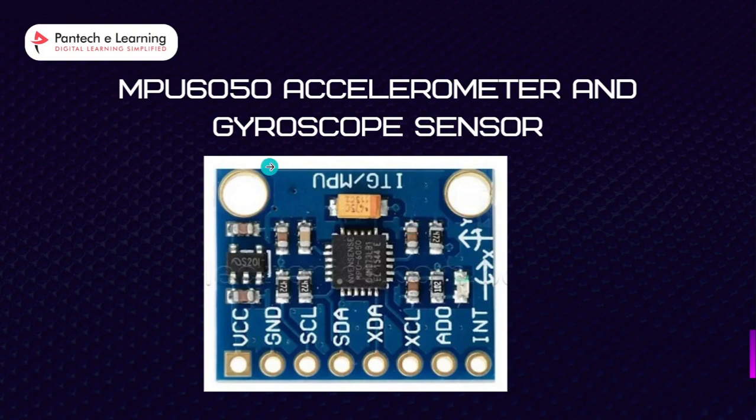Coming to the MPU 6050 accelerometer and gyroscope sensor, this is how it actually looks. This is the world's first integrated 6-axis motion tracking device that combines a 3-axis gyroscope, a 3-axis accelerometer, and a digital motion processor, all in a small 4x4x0.9 mm package with its dedicated I2C sensor bus. It directly accepts input from an external 3-axis compass to provide a complete 9-axis motion fusion output.